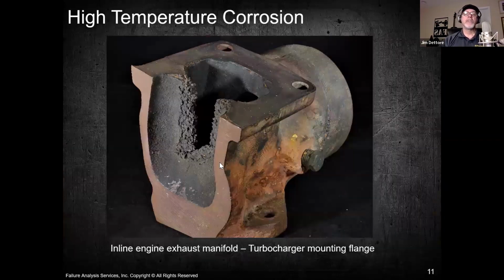And it just begins to oxidize. And we've got a lot of airflow coming through there as well. That's almost like hitting the oxidizer bar, and it damages this area. So this should be solid all the way across here. It should look just like this all the way across to prevent this exhaust gas flow from reverberating against this exhaust gas flow, so they can both exit upwards into the turbocharger.